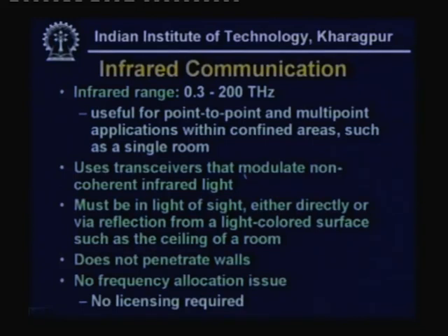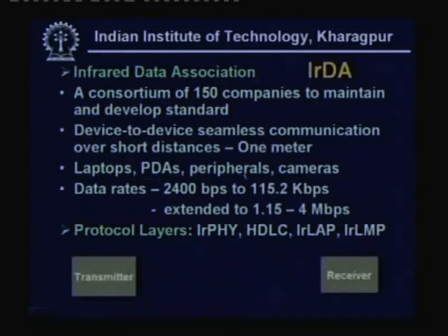One advantage is, in this case, the signal does not penetrate walls. So, secrecy can be very easily maintained. Another very important advantage is the frequency allocation. There is no frequency allocation issue. So, there is no licensing required.